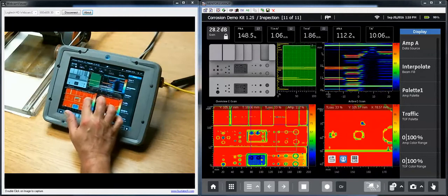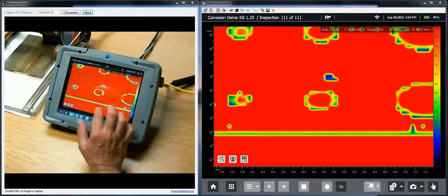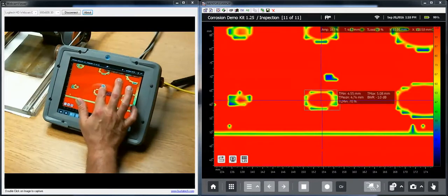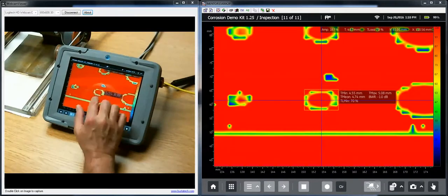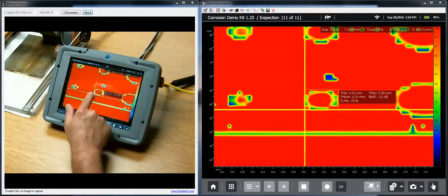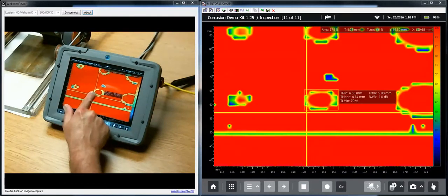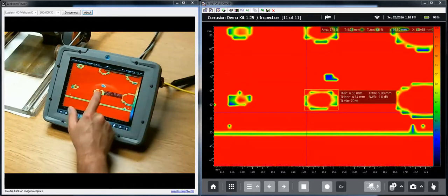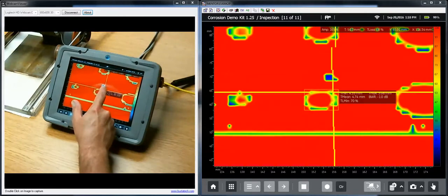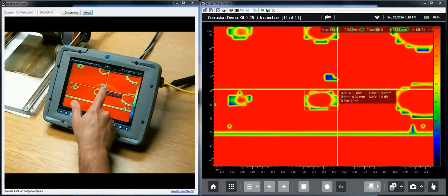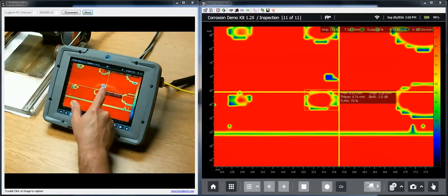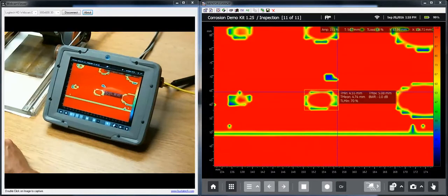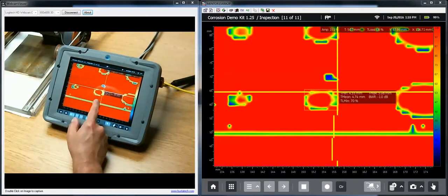and let's select one of these holes. All right, now if I come in here and just draw a box around the hole and kind of pick up the edges, I can also take my crosshairs, go to one corner of the hole. I see I'm at 56.5 millimeters up and 150 over. And now I'm at 156 over, 63 up. So I can pretty well conclude that's about a 6 millimeter diameter hole, give or take.